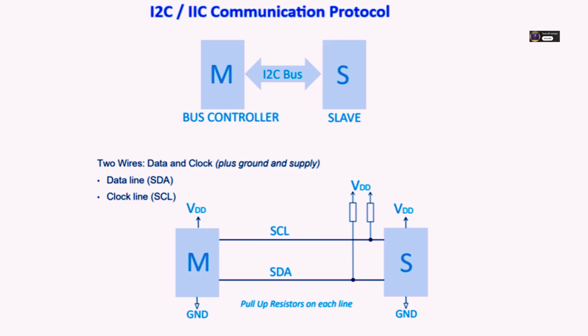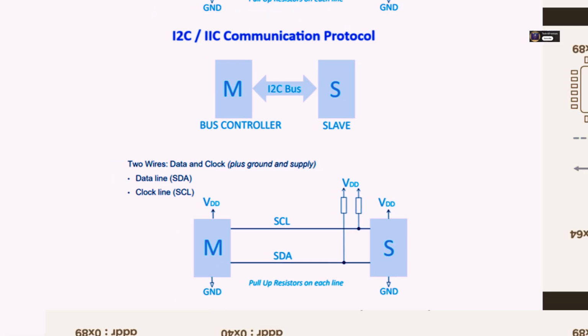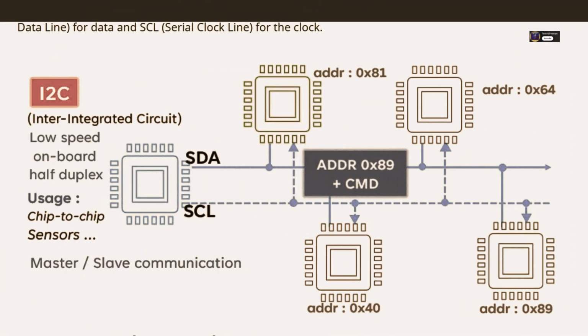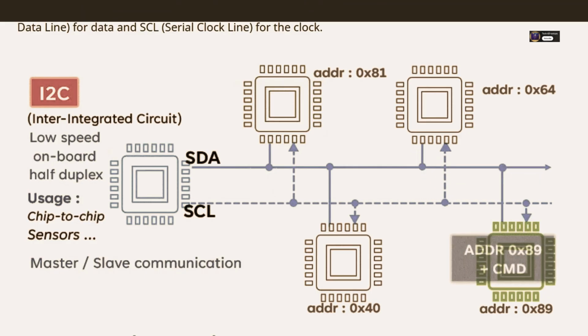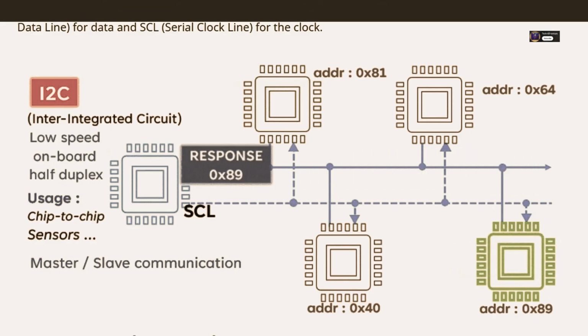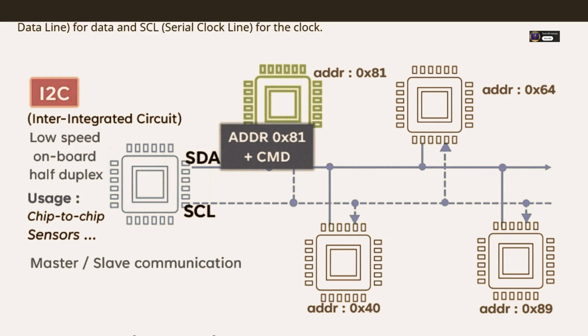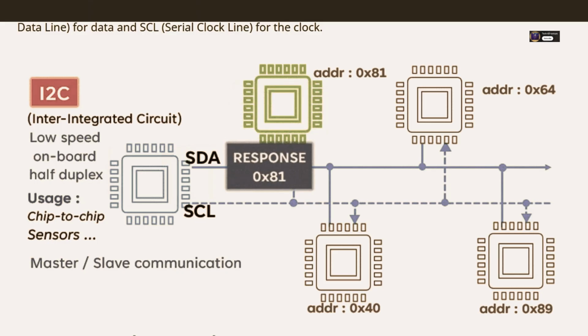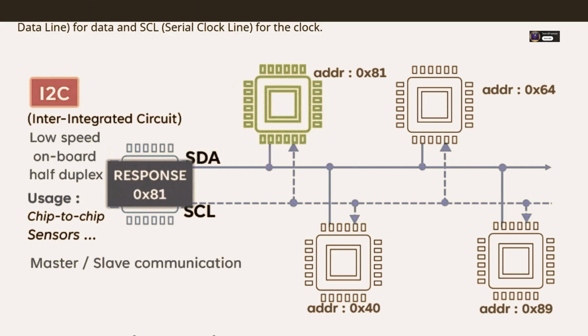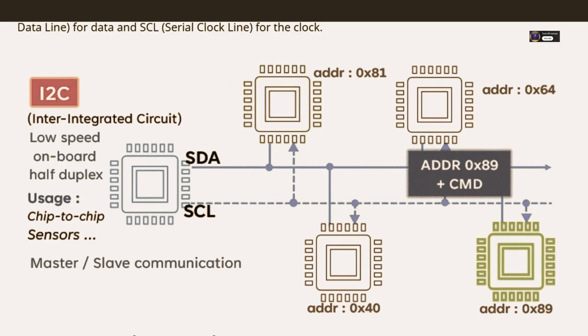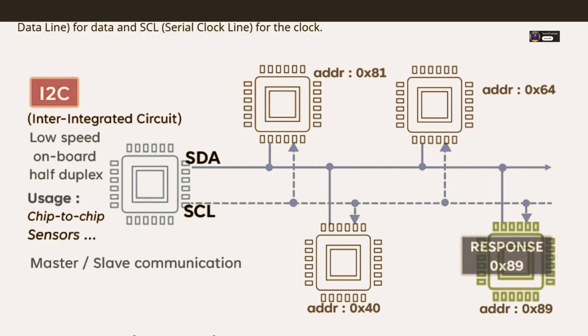Okay, let's start with the basics. The core definition. At its heart, I²C is a synchronous serial communication protocol. Right. Synchronous because there's a shared clock signal. Everyone's on the same beat. And serial because the data bits go one after another in a single stream, not all at once like parallel. Precisely. And it came from Philips originally, who are now NXP, way back in the early 80s.